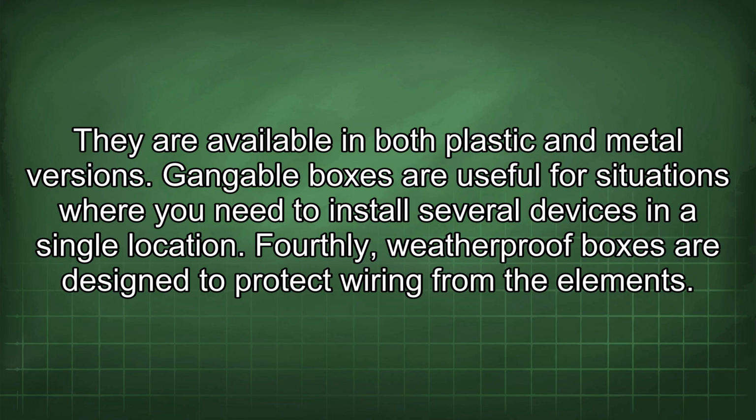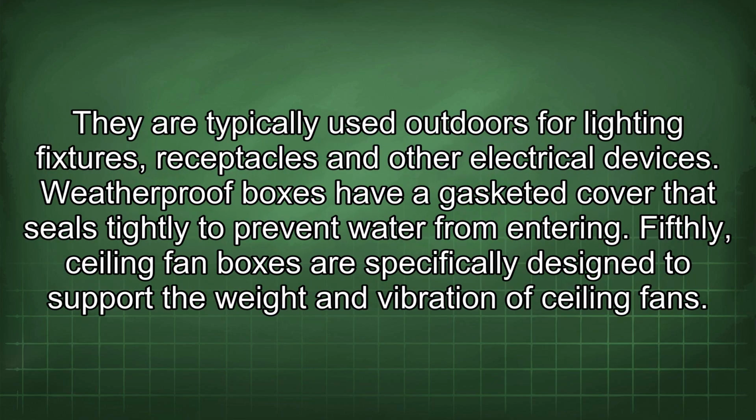Fourthly, weatherproof boxes are designed to protect wiring from the elements. They are typically used outdoors for lighting fixtures, receptacles, and other electrical devices. Weatherproof boxes have a gasketed cover that seals tightly to prevent water from entering.